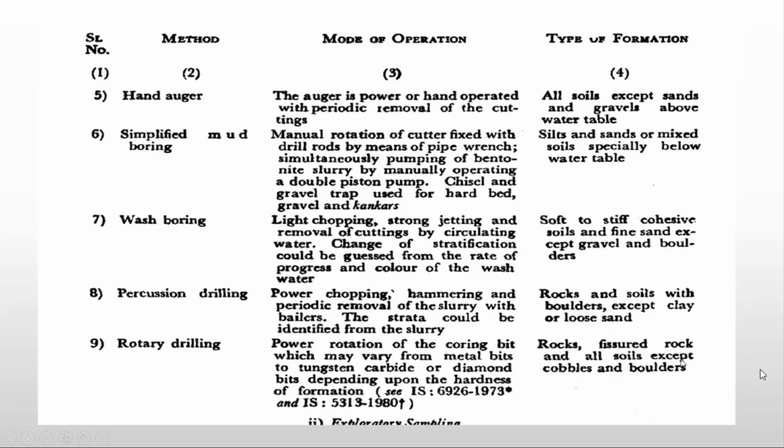So for every method, what formation you expect and where you have to do the boring, you can find a guideline that roughly points out which method you have to take, and thereafter you have to use your further judgment and refer to codal provisions on how deep you have to go.